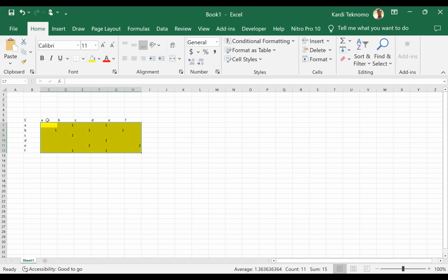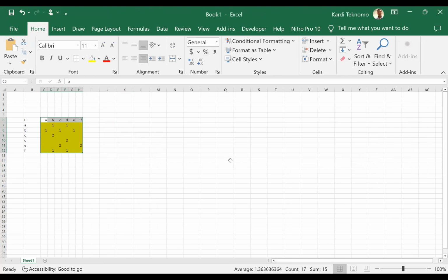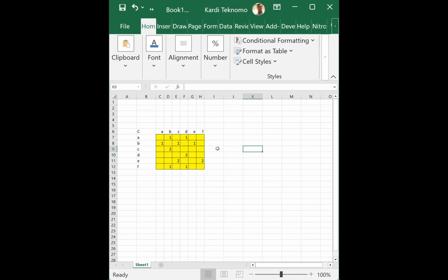So I put this yellow on the right side. If you want it to become neat, you can just format it. So we have the capacity matrix. We just type this based on the slide, right? So the same capacity, when you put it here, one lane is actually capacity per lane, say 1,800 PCU per hour, right? So we do it manually here.